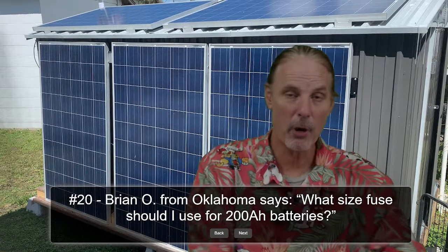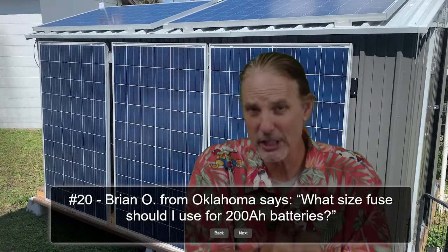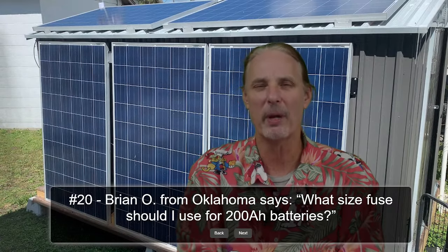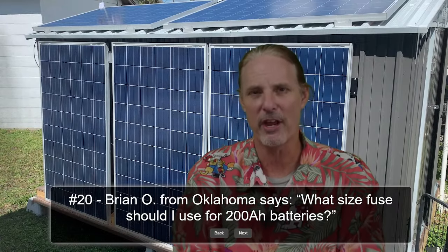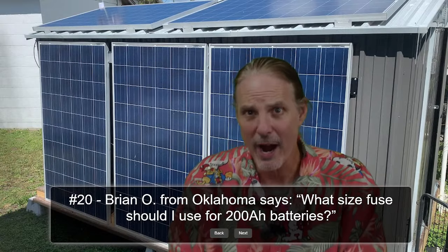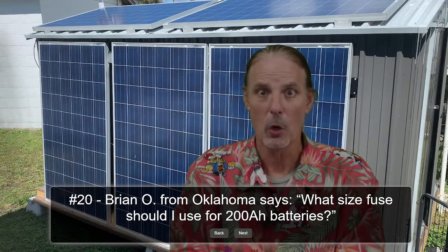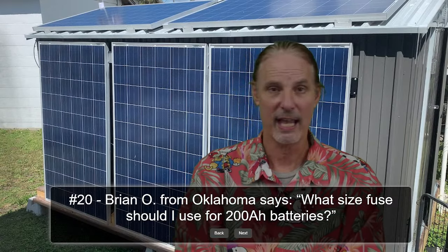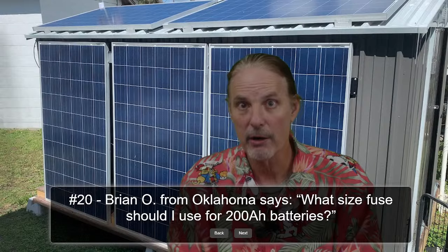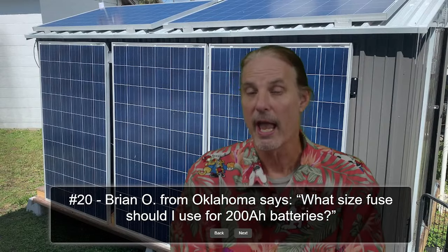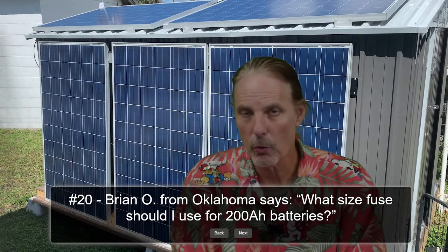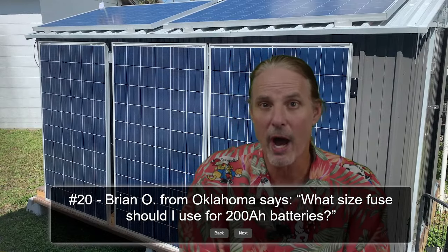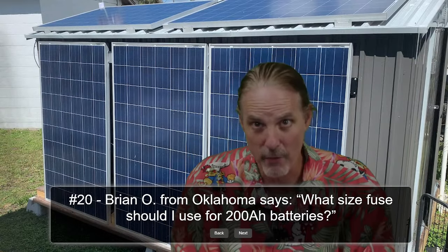Now, the second part of the equation here is usually the most important part, and that is fuses and breakers most of the time are there to protect the wiring from melting or causing problems. And that means that if you have, let's say, 8 AWG wire or 8-gauge wire, and you don't have larger wire, then you're going to want to build the fuse to protect the wire and the circuits around that wire.